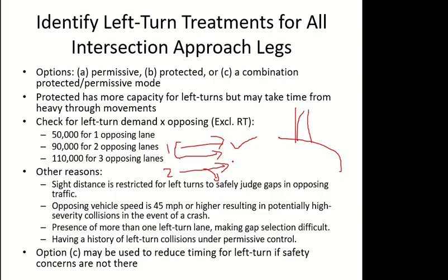Now for the design of the signal, all three lanes have the straight movement. So when I design a phase for the straight, all three lanes will move. All three lanes will have the cars allowed to move. But their V by S ratio is not the same.